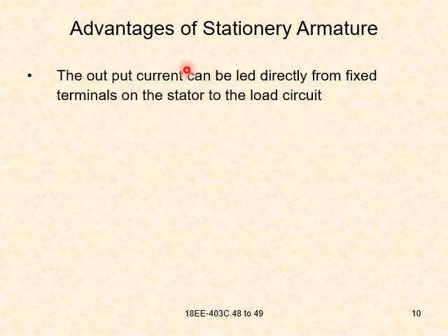That means it doesn't require any slip rings, brushes, brush holders or anything else. So there is no need of any slip ring, brush and all those things. The output current can be led directly from fixed terminals on the stator to the load circuit.